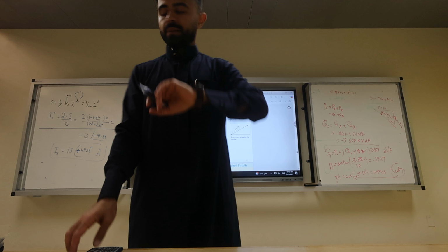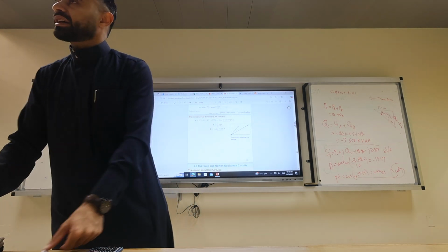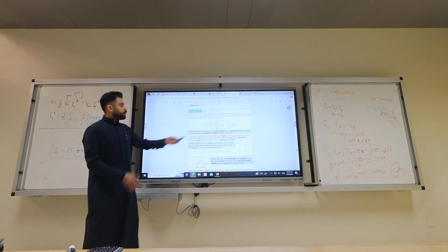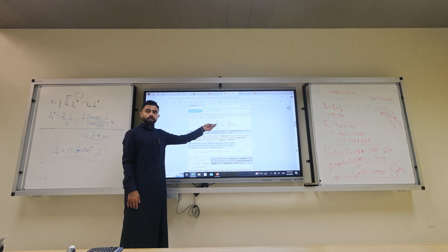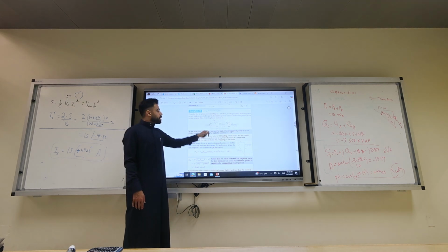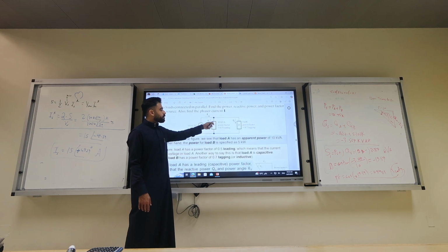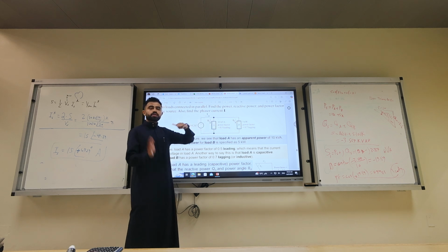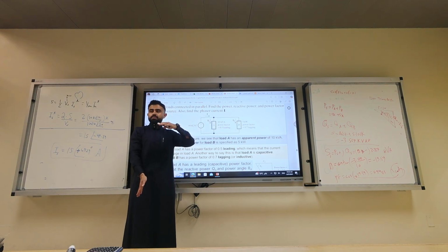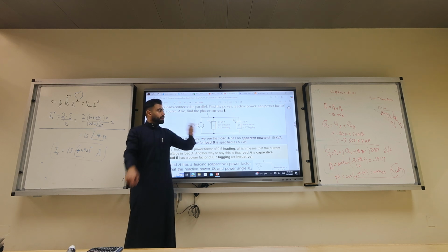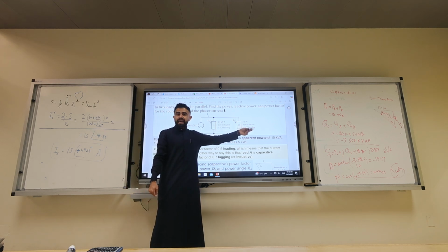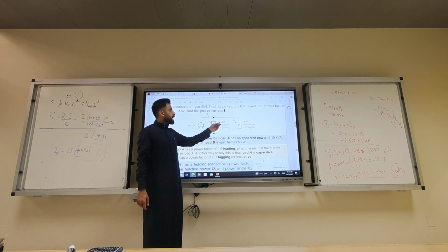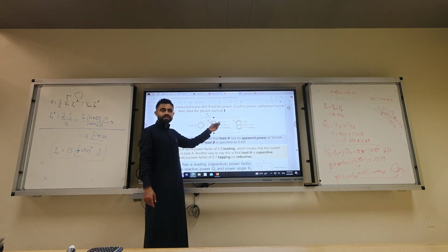Let me repeat that example. I don't care, we're late in the curriculum, but I don't care. This example again has a voltage source and box A and box B. Box A has a real power of P and it's leading. So this tells me it's a triangle with heads up or head down. It's heads down, negative angle. 0.7 lagging, it's heads up, so the angle is positive. Here I have P, here I have absolute value of S.